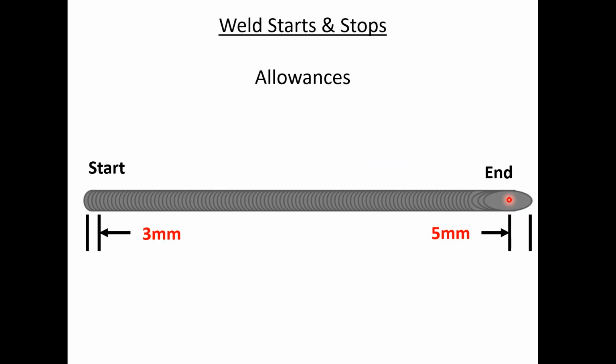So, sorry about that. At the end of the weld, I just want to say one thing. When they're defining what a weld should be, they'll say the weld should be as long, there should be enough weld here to meet the length that we are prescribing. What they've told us is we want this to be 200 millimeters long, and there has to be 200 millimeters of good weld. Now, there are specs out there, almost all, that give you a little bit of movement in this area. That is, if you've got a little bit of discrepancy, and sometimes that's why they'll make a weld a little bit longer, it shouldn't make any difference. I do want to point out one important thing, though. The crater condition. This is the crater of a weld. This is the end of a weld.